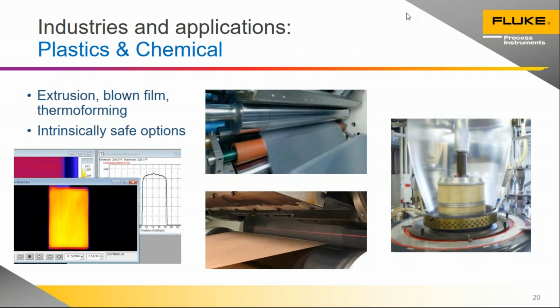Some applications may have 3 sensors, one middle, one on each side. The line scanner gives you an advantage in the fact that it's only got one detector. So really the difference is kind of absolute. You don't need to consider really the specification of 3 different devices, that they're allowed essentially to vary by 0.3% plus a digit. And if you've got really tight control, that can be useful.